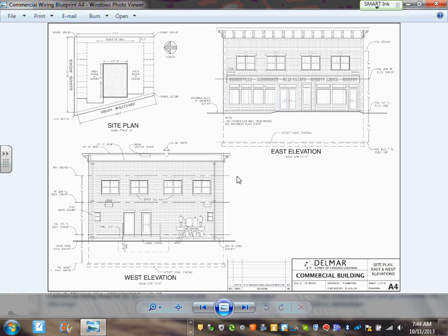Okay, I want you guys to assure me that you understand A1 through A4. So it's a commercial multi-occupant building, two stories with a basement. The two stories and the basement are shared between, I believe, five occupants. And we need to design a power, lighting and low voltage system for this building. When you are faced with a question like this, the first thing you need to ask yourself is what's common between all of them, so we can put them in a common panel. And what's not common, so we can put them in the individual occupant panel and meter. Cool? Any questions, guys, about these questions?